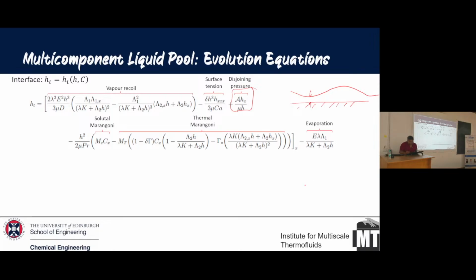To avoid that, I put in some kind of disjoining pressure. It can go as small as possible, but it has some sort of tolerance, and that is determined by the Hamaker constant. This is the point where it forms a precursor film. This is also a modeling device to stop the simulation from going mad, and it also shows some level of dry out. So we can say that the moment the height of the film becomes close to the Hamaker constant, or close to the disjoining pressure equation here, that is when you almost will have dry out.